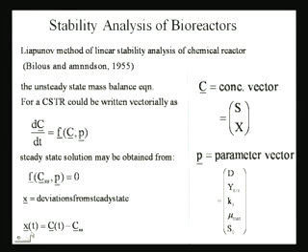So the deviation is a small deviation about the steady state. Is that clear? About the steady state, that has to be very clear. First, we obtain the steady state solution and then we give a small perturbation and then look at deviations around the steady state. So x is my deviation around the steady state, which is given as Ct minus CSS, CSS being the steady state and Ct being the current one in the presence of deviation.